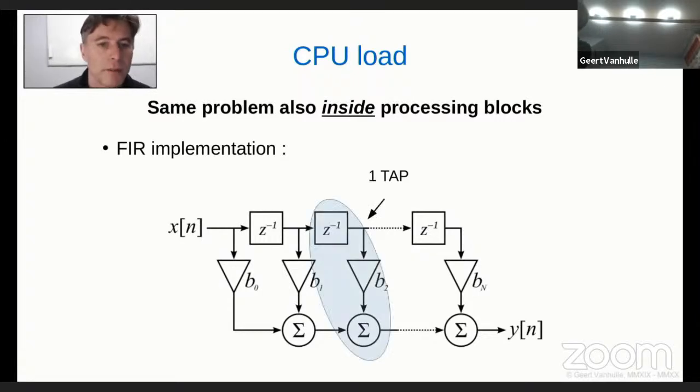These kinds of filters consist of taps. So you have one sample that is multiplied with a certain factor, it's delayed, and it's added together with the other samples that are coming in. Of course, these samples can only be processed when the previous one is already processed. No?